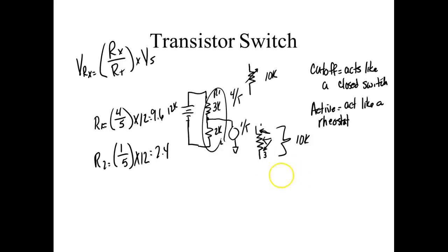So if I come over here and use a bipolar transistor in the active region, we come up with this circuit right here. The transistor acts like a rheostat, but we're controlling the rheostat electronically. So if I take my output across the transistor, then I can vary it anything I want to. If the input is coming over here doing this, then the output can do this. It's going to be a mirror image, but it's going to have gain.